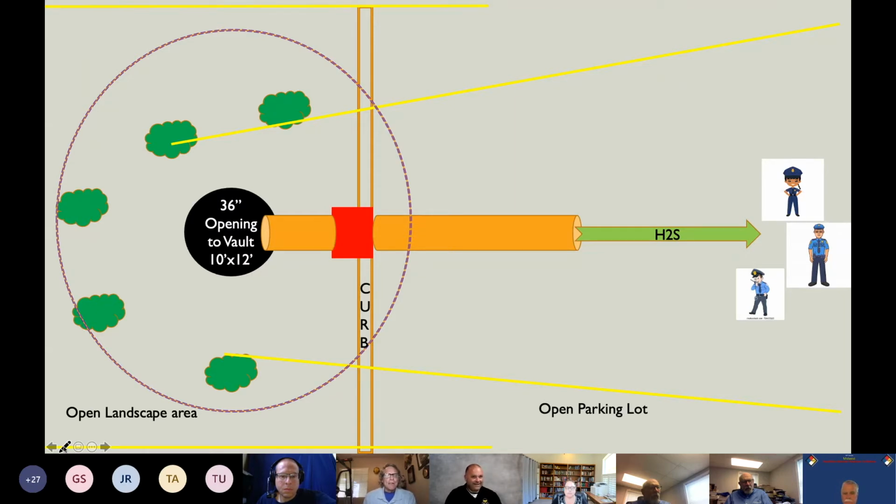Another reason, and going back to where our initial hot zone was, that circle, the other reason we did that is operating in that area, we have a hazard that's below ground. So we're defining this area and we're putting physical tape up because I know this sounds very unlikely, but I would never say never, there's always a possibility someone's not paying attention and they walk into that hole. So in other words, anybody coming into this area, this hot zone, needs to have their head screwed on straight, needs to be in proper PPE, needs to be aware of their surroundings.